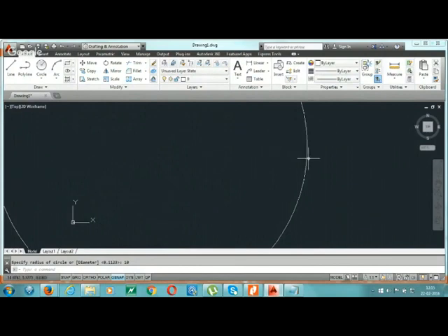This I can do with the help of the zoom command. Either you write Z here or go to the main menu from where we can select the Z command. There are various types of zooms you can do: zoom all, center, dynamic, extents, previous, scale, window, objects. In this case I am taking zoom all. I will say A to it and just give enter to it.